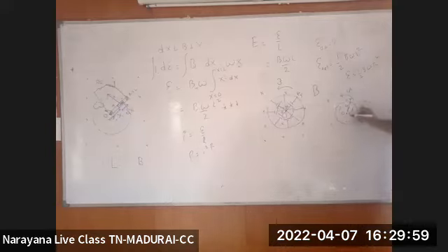For your understanding, I will take this as 0 volt and this as 2 volt. Then every terminal is having 2 volt only. If you connect any bulb between any two end terminals, will it be glowing? No. Why? Potential drop: 2 minus 2 is 0. So there is no potential drop, which means if you put any external resistance between two terminals, no induced current will flow, no electric field is induced, no power will be dissipated. I hope everyone understood very well, right?